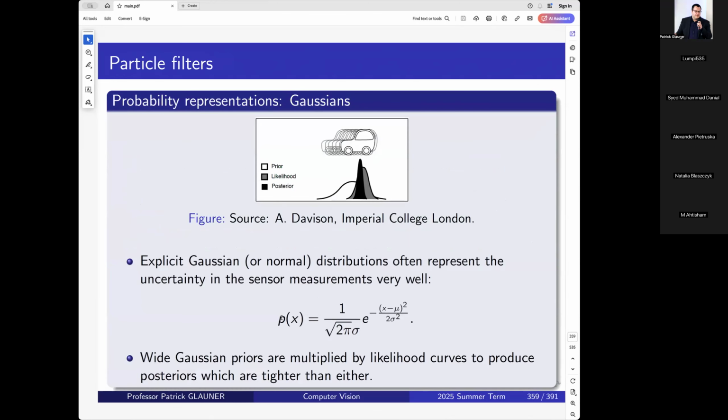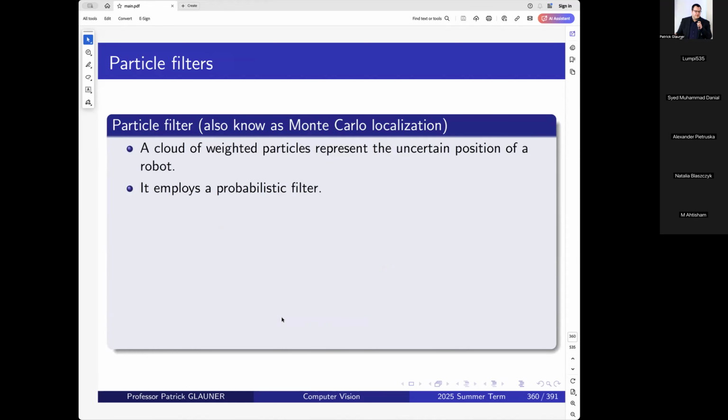And we use the Gaussian distribution to model the uncertainty for the sensor measurement, because not every sensor measurement is probable. Maybe there's suddenly just some very unexpected value coming from the sonar. It's still a measurement, but uncertain, and it's very unlikely. So a Gaussian distribution helps us to reflect if that's likely or not, and how much we can plug it in when we do our state estimation.